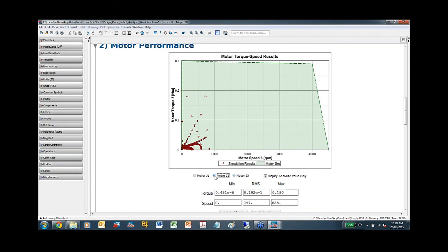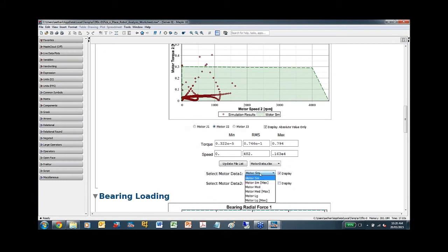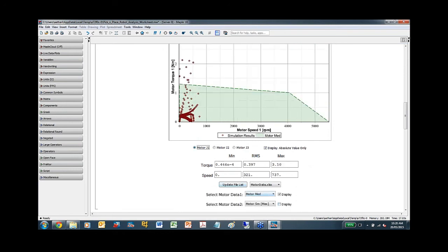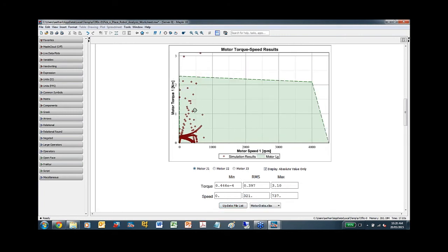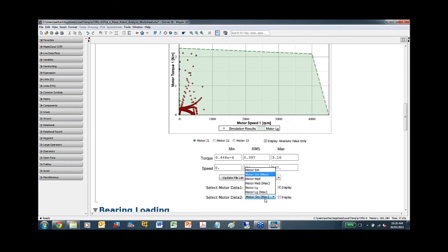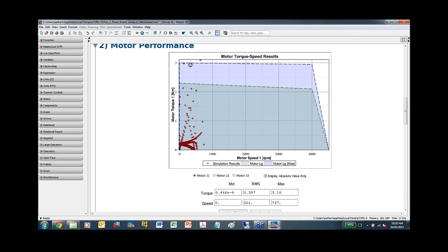So if we go back to joint number 2, maybe in our motor list we can choose another motor which also matches with that, which is the medium motor. But for joint number 1, I believe the large motor is going to cover most of the operating characteristics within the normal operation envelope or region. But still, I believe we have some points on the boundary, which means we have to go with a larger motor, or we can change the configuration of our robot to match this motor.